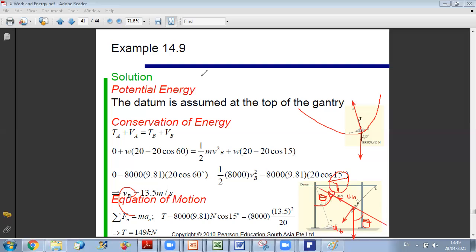Okay, so I will write that the sum of forces along UN is equal to, first we have the tension T, plus T, and we have the projection of the weight. The projection of the weight on UN is in the negative direction, and it's minus W cosine theta. So minus W cosine theta equals M AN.